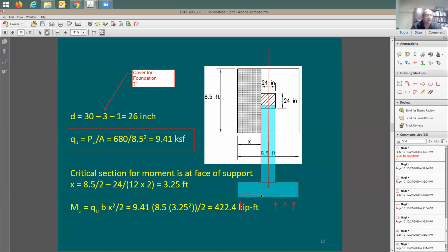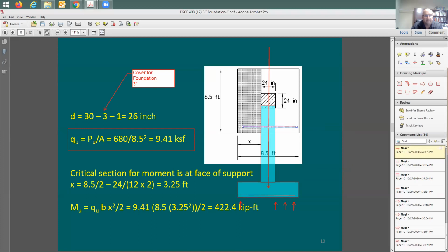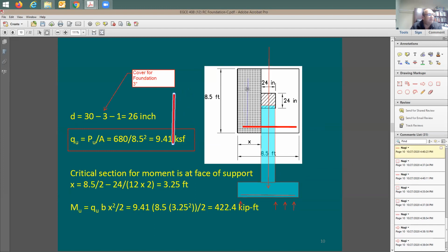You're going to say, is that it? I mean, how about the reinforcing bars? Are you going to be providing reinforcing bars only in one direction? So let's look here at the plan view. In the plan view, this rebar that you're looking at, I can draw it this way on the footing. Here's the rebar in this direction, right? Let's say, here's the rebar. It's going to be running this way, correct? Which is this rebar. Just show it in the plan. And the rebar running in the other direction, I can also draw it like this. Now here's the rebar running perpendicular to it at the bottom also.